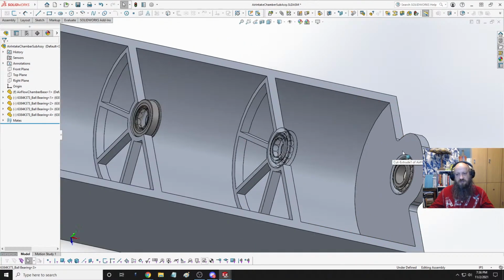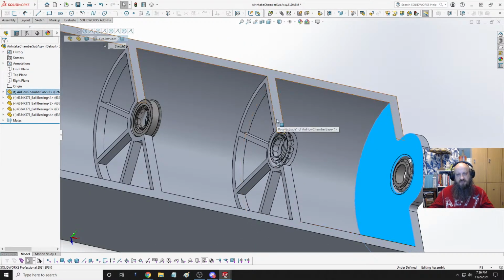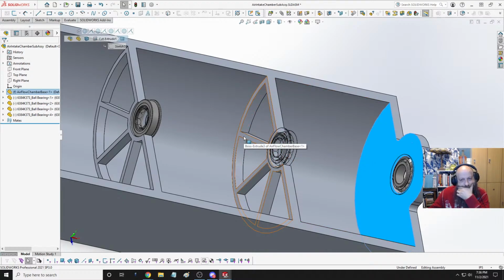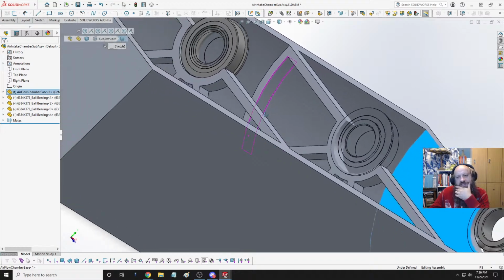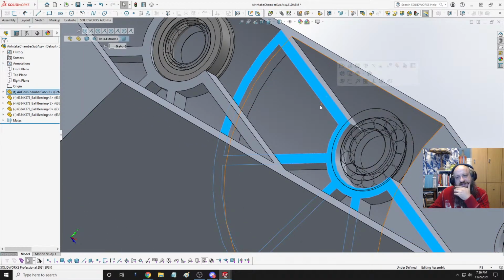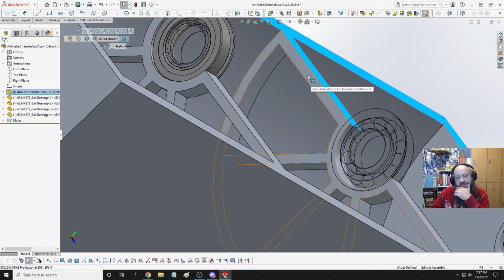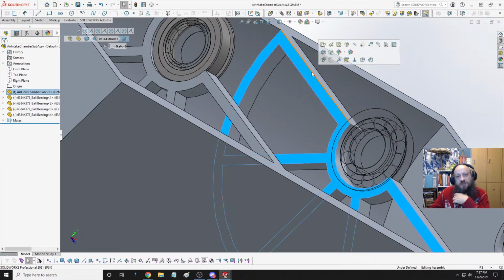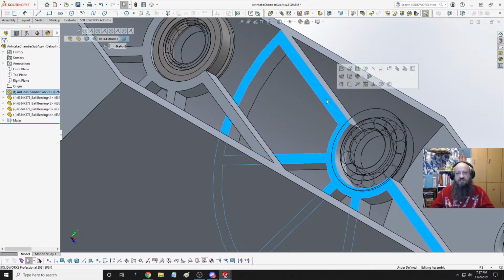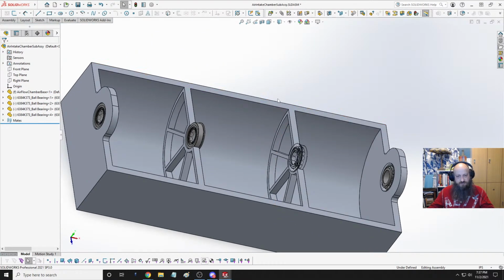But I guess I could make this feature through here. We would also have to have this cutout in the top. I have to think about that. Oh, you know what else I didn't think about? This will have to be half as thick as this for when I put the second piece over the top, so that it maintains the same thickness all the way around. These ones will be double thick. Let me fix that real quick.